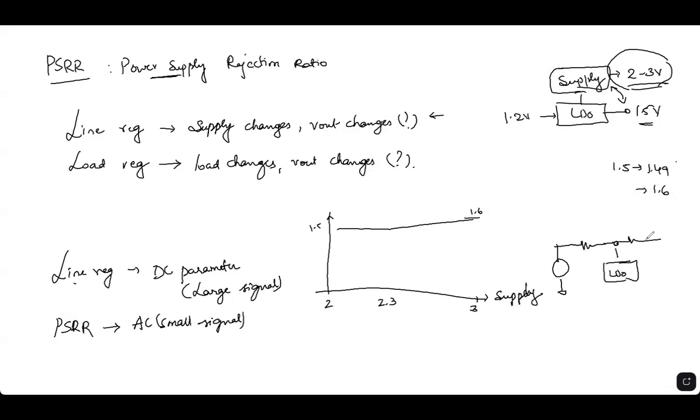There could be some more where you tap it to the oscillator, some more points where you tap to some other loads. So 5-6 loads are there, and there'll be 5-6 tap points. Now, the issue here is that, let's say your oscillator takes the current in bursts, more like this type of current. Whenever the oscillator switches, there will be huge current. So if this huge current has to travel through this resistor and through this resistor, what does it mean?